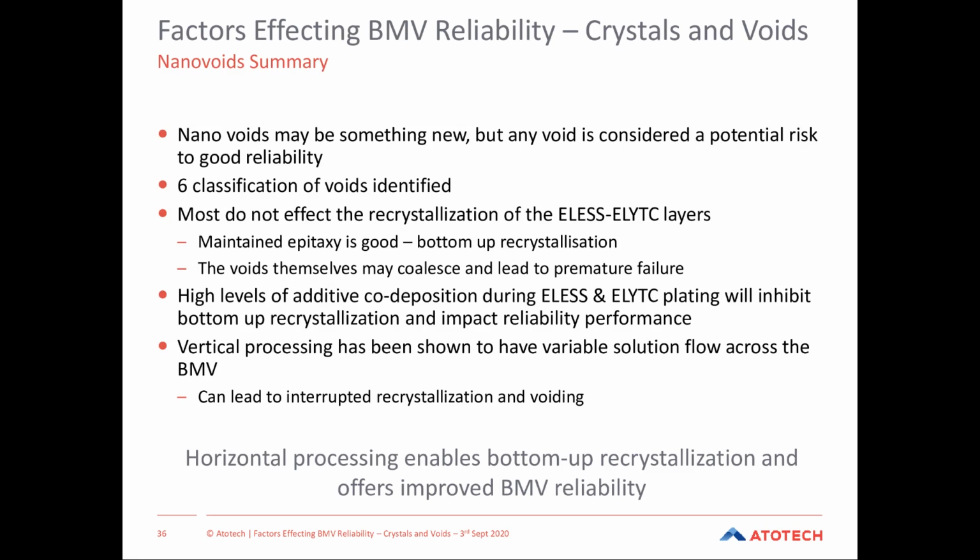Those voids that form are on a nanometer scale, so they are tiny, but voids coalesce. And when they coalesce, they grow. And as things grow, they are more likely to act as crack defect points. As I said, the co-deposition has to be taken into account in exactly the same way as it does for recrystallization.